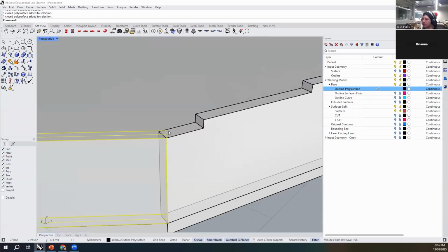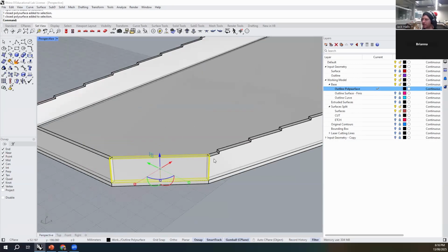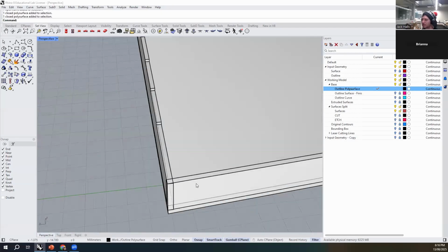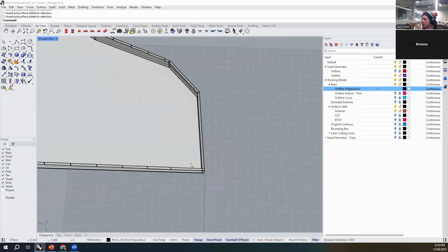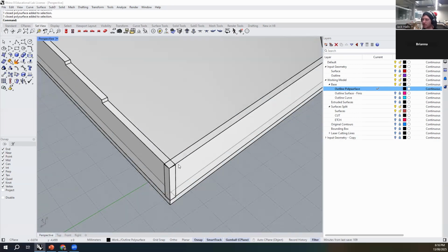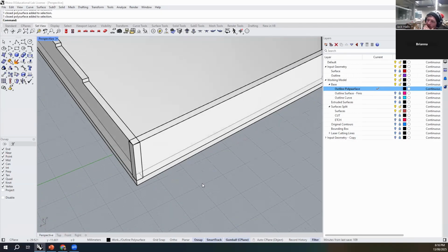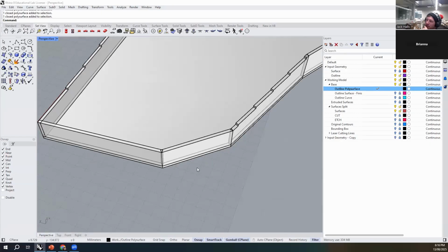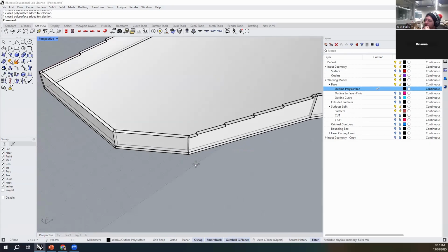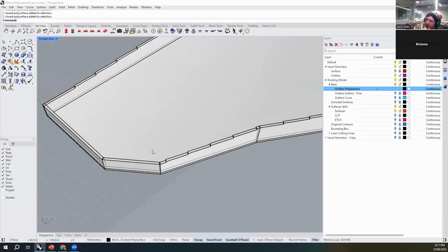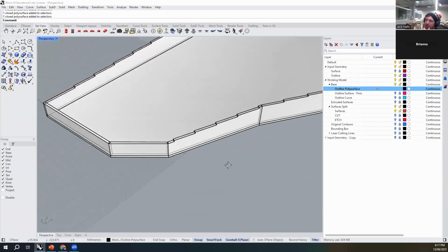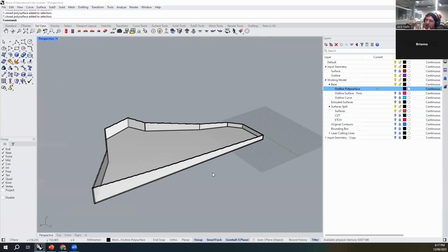So as you can see, importantly, how these things intersect, because if we extruded them off the face, this is where the complexity of these non-standard edges comes from. Nothing in here, by the looks of it, is actually a right angle. And that's okay. It doesn't mean that the model can't be made. It just means that, like I said, those joints aren't necessarily going to be the prettiest, and we have to accept maybe a little bit more of a loose way of joining things together, and then use something like a cover strip and some other components to ensure that it's structurally viable and aesthetically what we want to do as well.